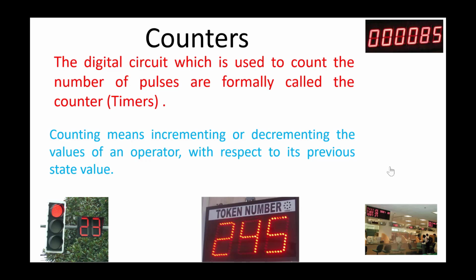So where you are going to send light from one side of the conveyor belt to the other side of the conveyor belt. In the middle you will be moving your objects, maybe bottles, maybe products. Whenever light is obstructed, your counter will increase its count by 1. So it is indirectly measuring the number of products that pass through the particular belt.